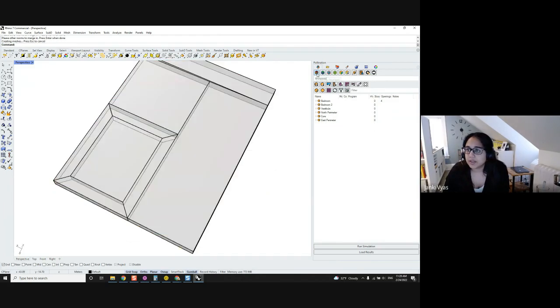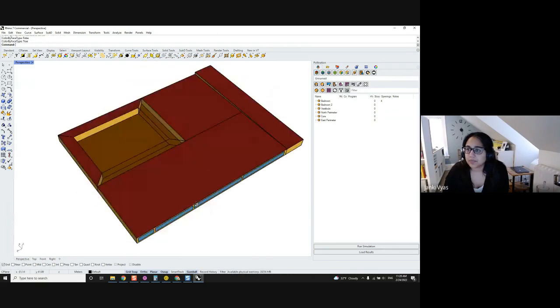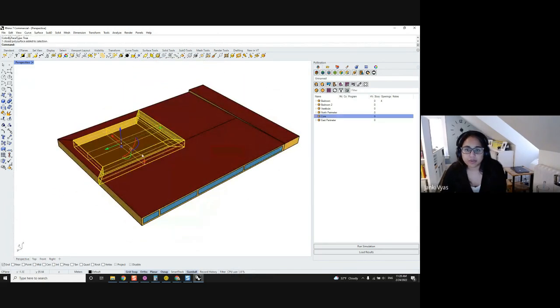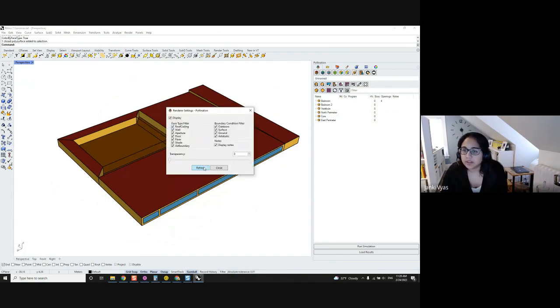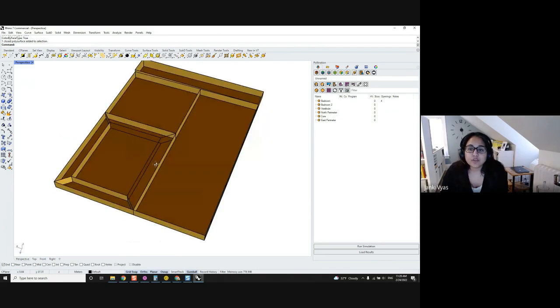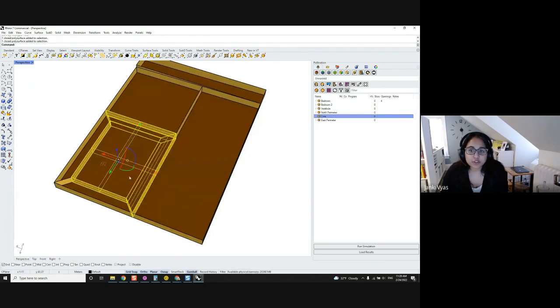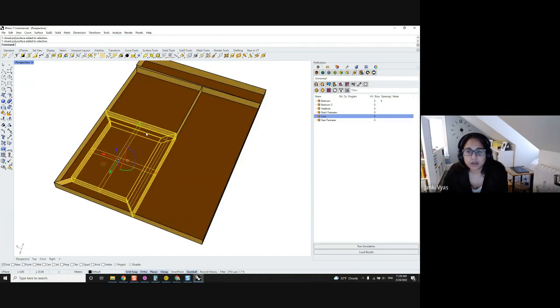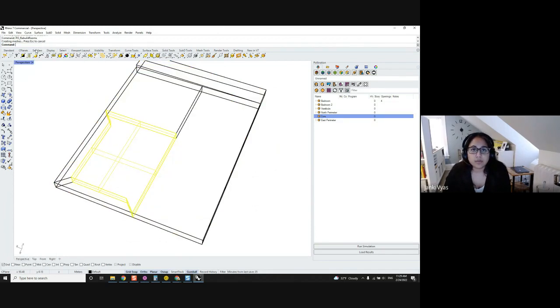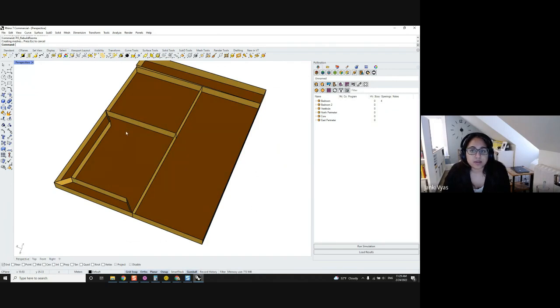And let's just see if there's a little bit of a bug with the preview here. Let me just go back and refresh that. There you go. So now you can see that that's actually merged in, but you can still see where that old room used to be. If you don't want to see those lines, we have a command called PO rebuild room. And you can hit P, and now those lines disappear, and this reads as a single room.